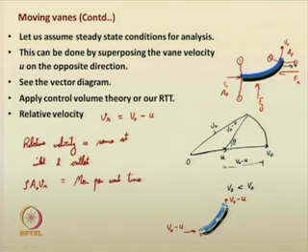Fine. If you connect some series of vanes like this, say in a circular disc, and if you rotate it, then all the jets that are coming into the portion will be captured by any one of the vanes. Then you can subsequently suggest the discharge from the nozzle, and these quantities are the same. So, we will be analyzing using the same control volume approach now.